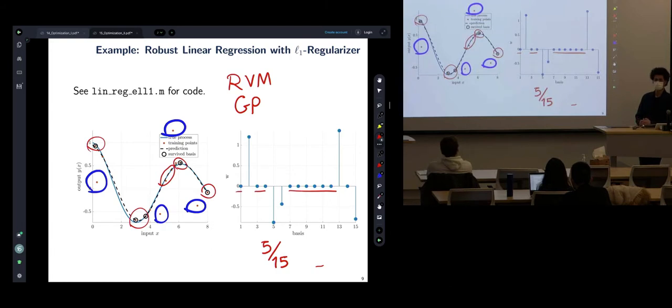The fact that the laser beams go through transparent objects will give you an outlier. There is a window, and you will hit the window as an obstacle, but the laser is telling you the obstacle maybe is 10 meters away instead of 5 because there's a wall behind the glass. So that's an outlier, and there is no way we know it.